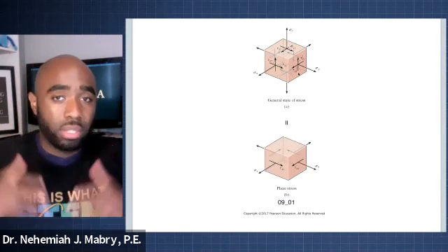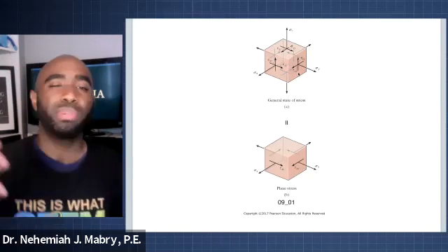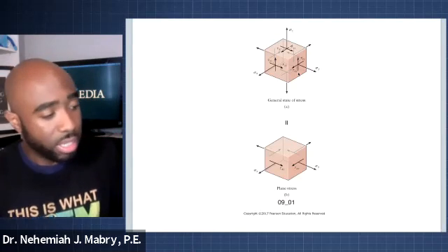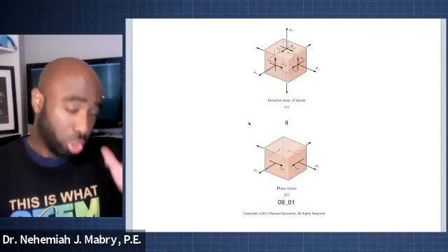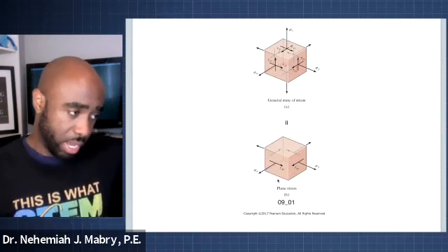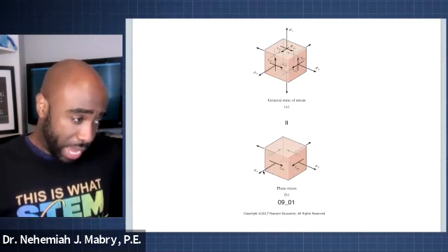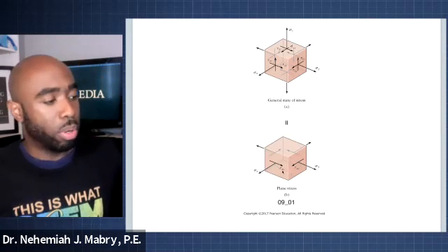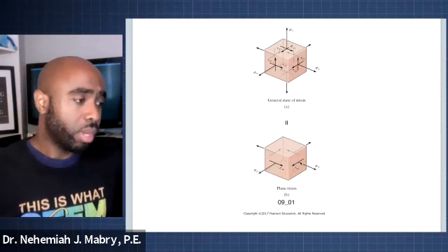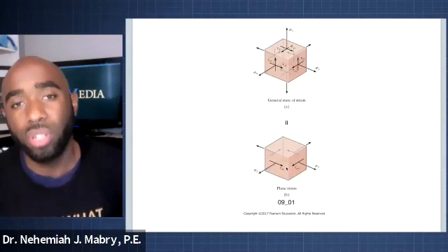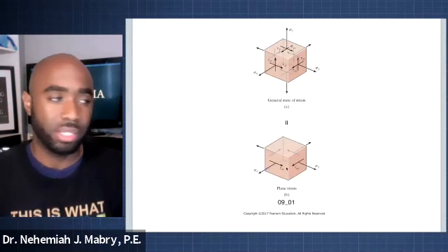Now, one of the things we do in this class, at this level of mechanics of materials, is simplify it a bit. We don't just look at this general state of three-dimensional stress; we look at what we call plane stress, which is more two-dimensional. So looking at this cube at the bottom, we have a normal stress of sigma sub x coming out of the x face, and sigma sub y coming out of the y face. And then we have two shear components, tau sub xy, and on this side we also call it tau sub xy, because these equate to each other when the object is not turning, when it's in equilibrium.